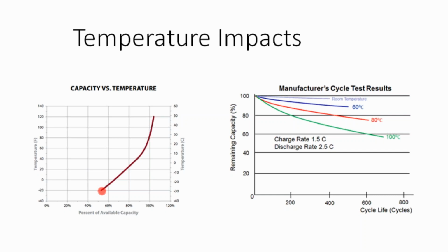So, they're up there having a blizzard today in Wisconsin. You put your batteries in a battery box outside. It can get into negative temperature weather without freezing the battery, as long as you keep the battery charged. Now, I think it would be better to have a battery box that has thermal mass in it so that you can heat the thermal mass up a little bit during sunnier weather, and then try and keep that battery box from dipping below zero even when it's below zero outside.